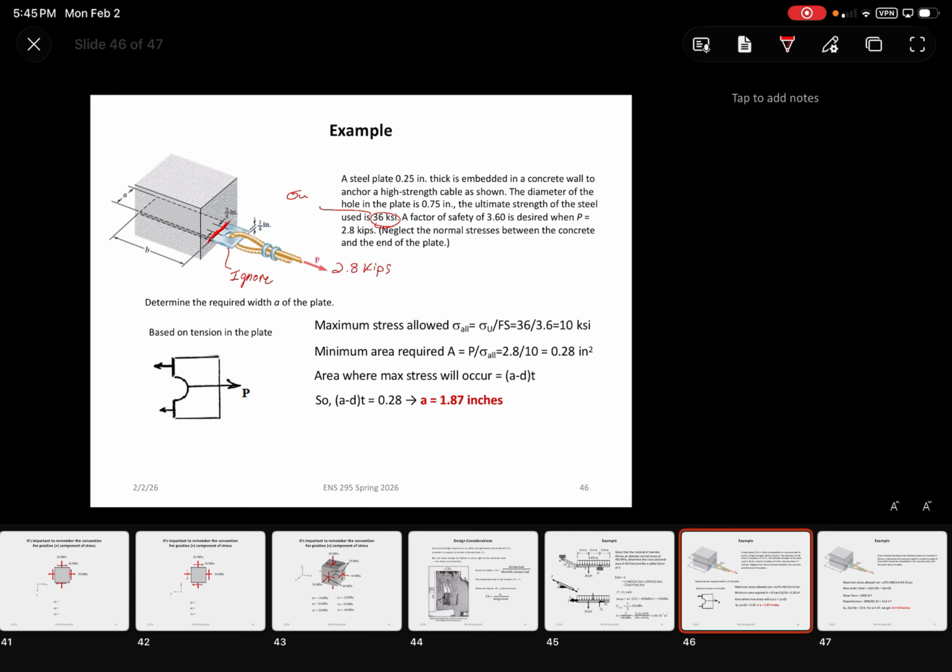And from that, we first need to know what the area is. So, how do we find the area? If we cut a cross section directly through the plate, and we call this the cut, and we look at the cut here, what we will have is a dimension A, and the thickness of the plate we know is 0.25 inches. Everyone sees where that section comes from, right?